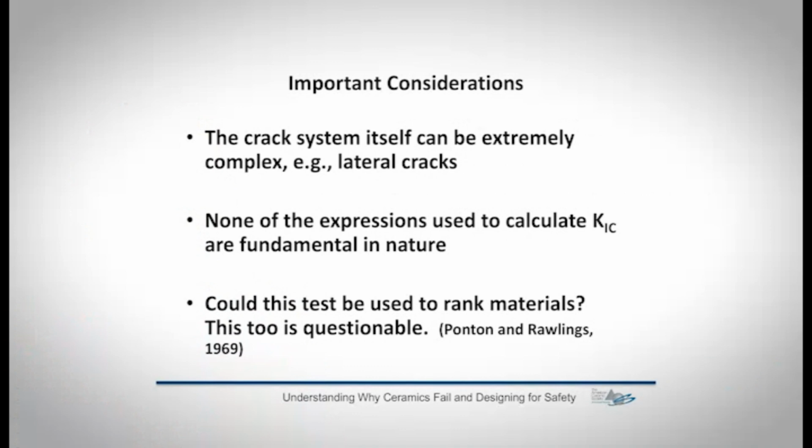So let me talk about a few considerations when you're using this test. Maybe it's the only test available to you because you have very small pieces of material and you need a number. And this test will give you a number. But the inaccuracy can come from a number of reasons. One, the so-called lateral cracks, which are parallel to the indentation surface instead of being perpendicular to it, can change the damage zone and therefore change the driving force on the crack.